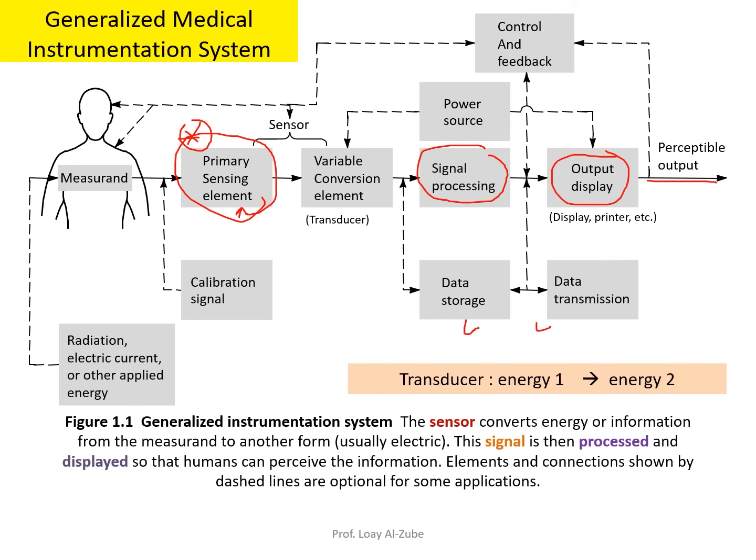And then you can do a calibration signal. Calibration is something that you need to do as an engineer in the hospital. Before anyone can use a medical device, there is a calibration procedure to make sure that the device is actually measuring what it's supposed to measure and giving you the right numbers. If you are hired in a hospital, your job will be preventive maintenance and calibration most of the time. We don't do repairs. You're not going to fix something in the hospital. We usually outsource this to the company that made that device, and we will have maintenance contracts with them. So that's how the model works.